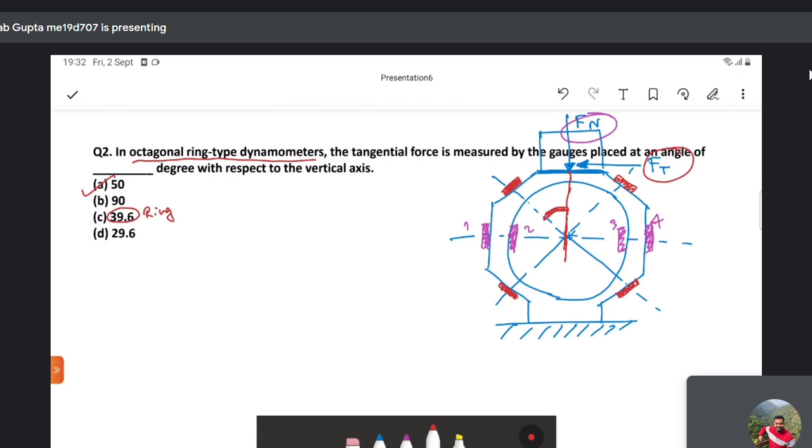So how do we calculate this, or rather how do we ascertain these values? We generally place the strain gauges such that we get a sensitive reading out of it, so that with small changes in the loads, it records a change in voltage, and we can measure that, and from there we can calculate the value of forces.